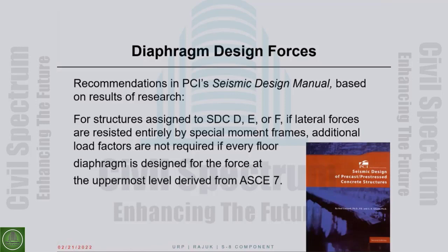So design category D, entire seismic force resisting system consists of special moment frames. You design all the diaphragms for the roof level diaphragm design force. You don't go down the height of the building. You design all the diaphragms in the building for the roof level diaphragm design force.